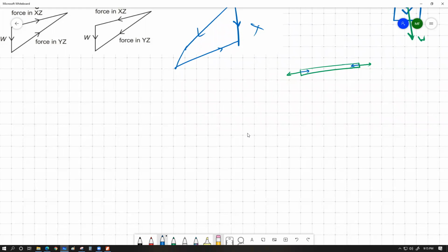Thank you. So the idea is that if you have multiple forces producing equilibrium on an object, and we draw a vector diagram with all the forces with appropriate scale and direction, placing all the forces one after another, you're going to end up with a closed polygon. In this case we have three forces, so we should have a triangle, but all the forces should be in the same sequence. All the forces produce zero resultant.